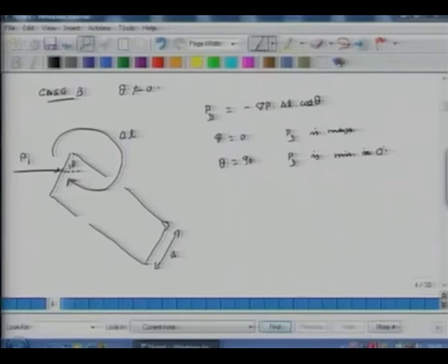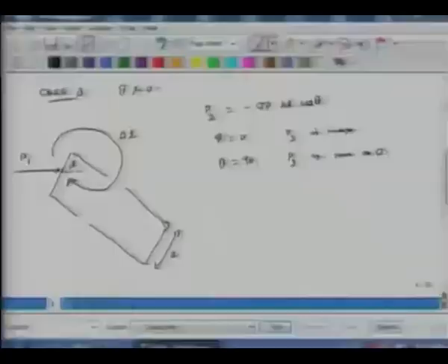So in this kind of contraption, I am measuring the movement of the membrane, which is basically a consequence of the difference in pressures attributed to a delta L. So that's why it's called a pressure gradient microphone.